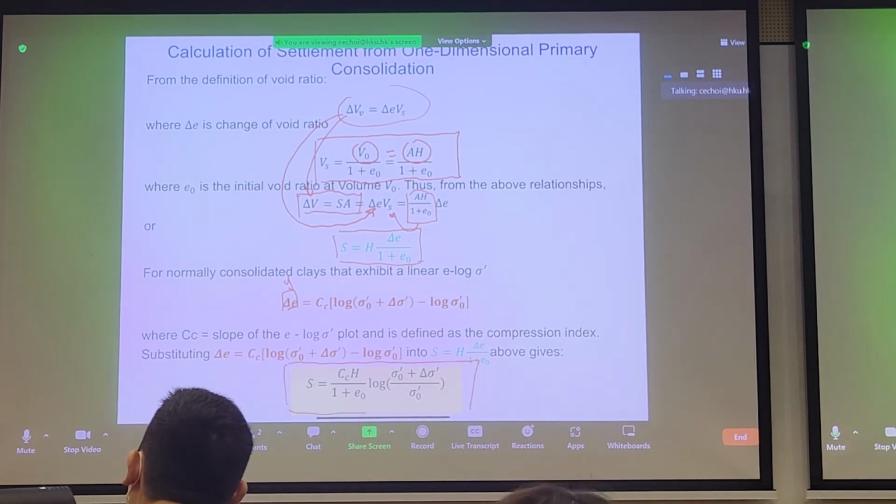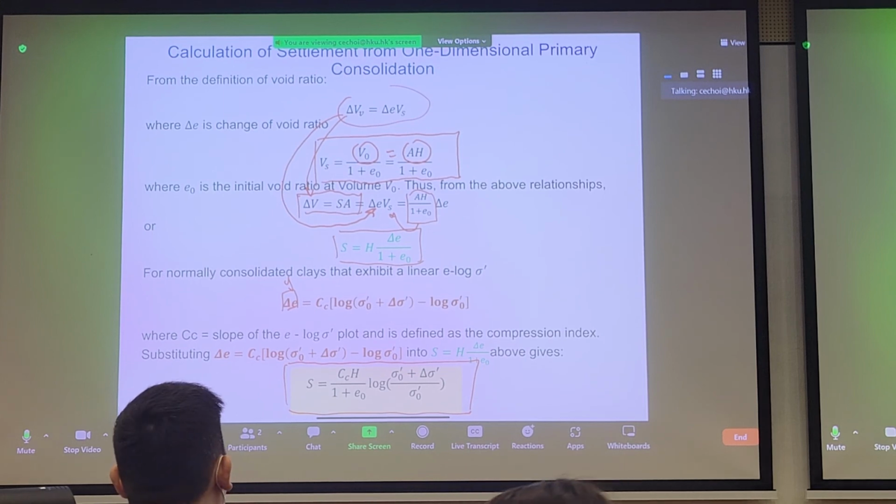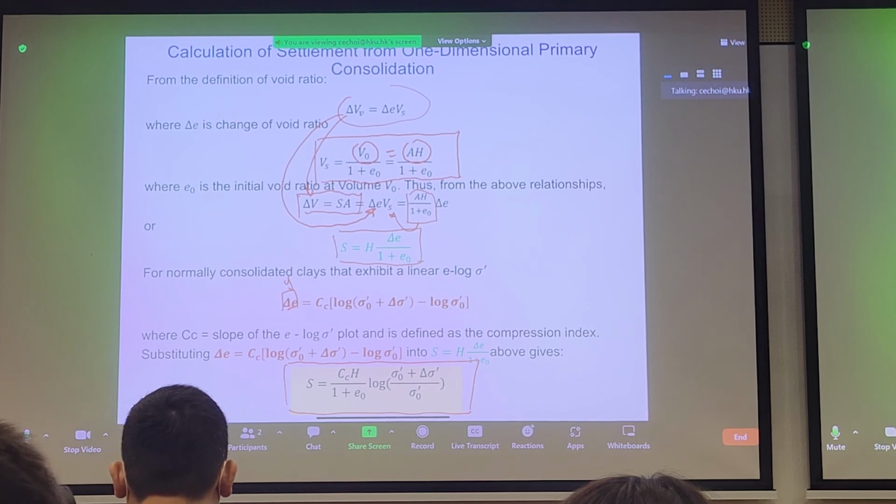And this is really nothing complex. This is just a linear equation substituting basic mass volume relationships. So on your own accord, this week, you can try to derive this once. And without these slides, you can probably do it. And you'll arrive at this equation here. And you can use this equation at the bottom in the yellow box to predict how much settlement from the